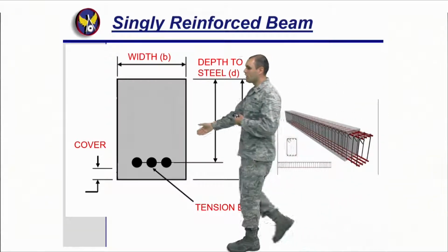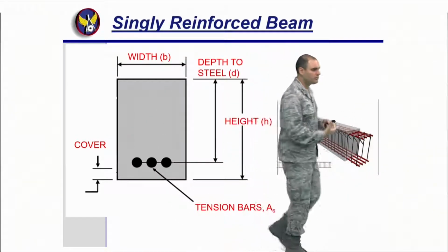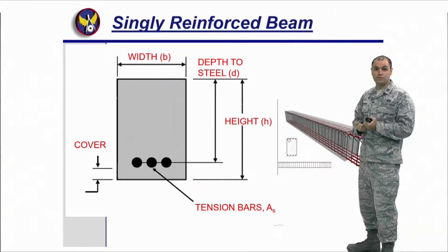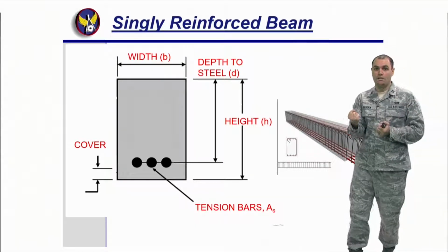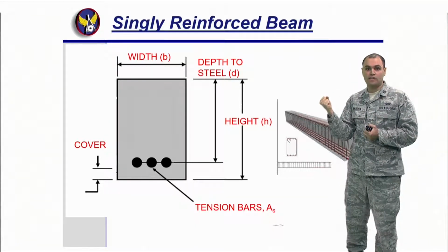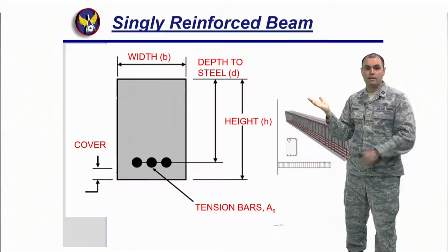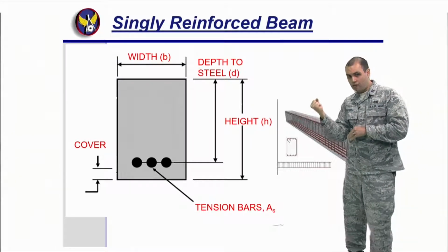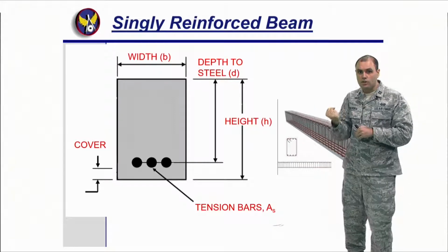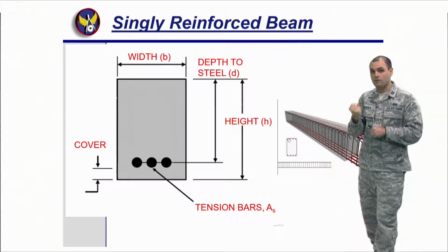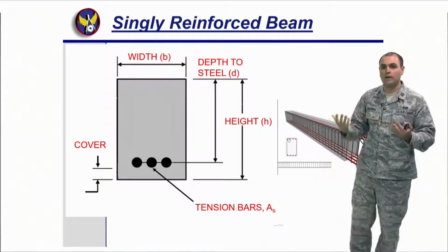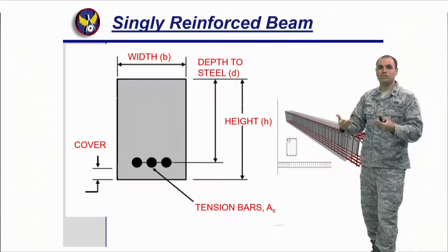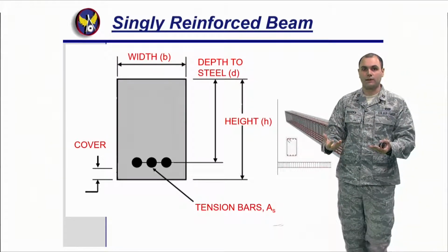And then you see over here a cover. What is the purpose of a cover? Well, the rebar that I'm going to put in my concrete to make sure it's reinforced needs to hold on, right? Just think that you're holding a rebar with your whole hand. Now say I want you to have the same strength with just your bottom hand. Well, if you didn't have a cover, that's what's going to happen. You're only going to have your bottom hand, and you're going to be able to pull. But if you have concrete around the whole rebar, you're going to have a good bond, is what we kind of call it in concrete. A good bond, so I make sure that the rebar doesn't pull out, all right? Because in the end, you'll see, I'm going to talk about it in a second, I want my steel to fail first before my concrete, all right?